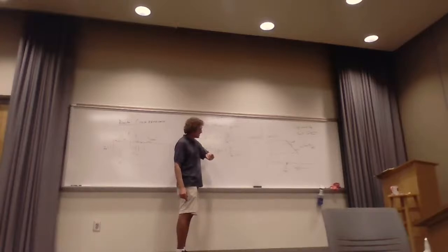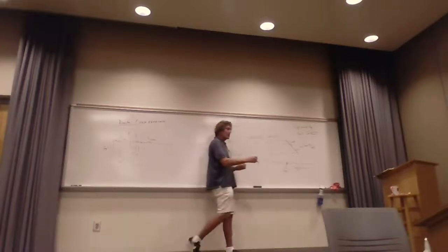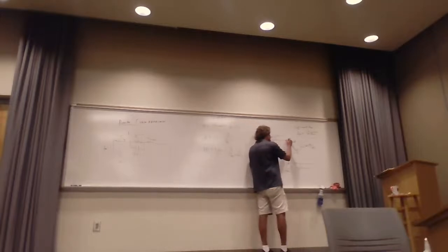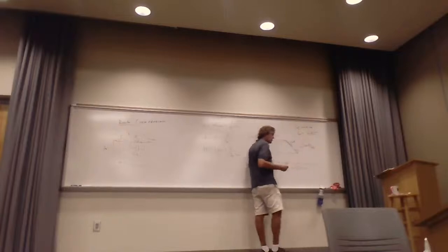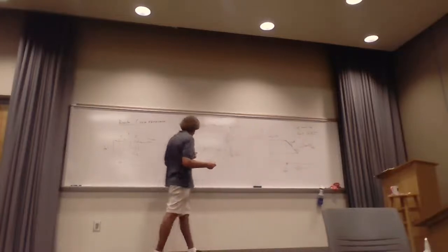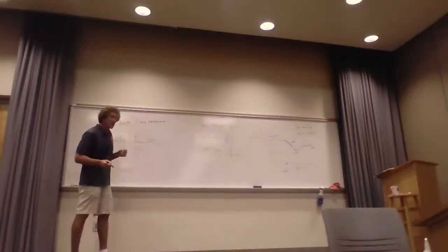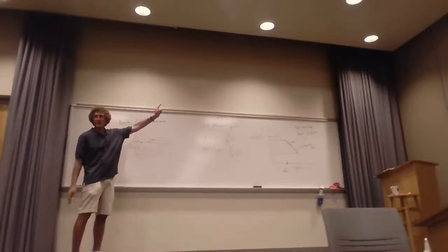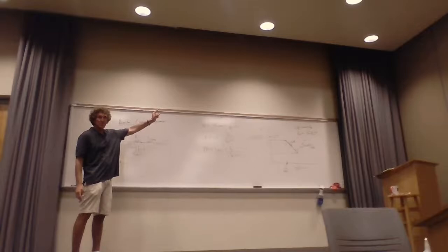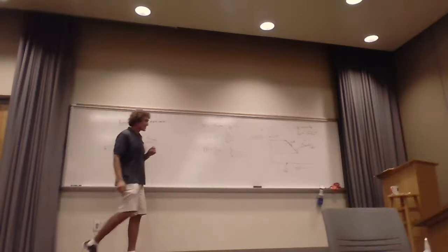So that's what a resistor looks like. A resistor at low frequencies looks like a resistor. Then there's going to be the first cut frequency here. It'll start going down at 20 dB per decade. Then it'll hit the self-resonance. Then it'll start going up at 20 dB per decade. And if you look at this thing, because I do have that wire, as frequency goes to infinity, the impedance is going off to infinity as well, because of that inductance. Agreed, class?